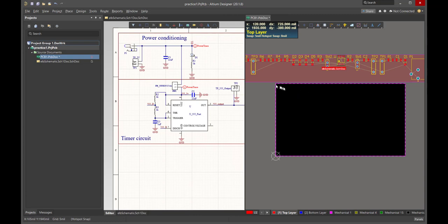When we are looking in the layout screen, we have all the parts labeled with their reference designator and their footprint. And they're all sitting up here with these little ghost wires that indicate the connectivity. The first step is to move all the parts over to the outline of the circuit board in the way we want them to appear on the board.